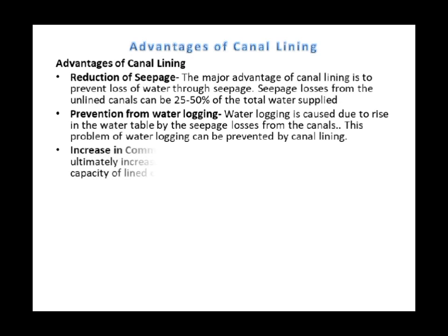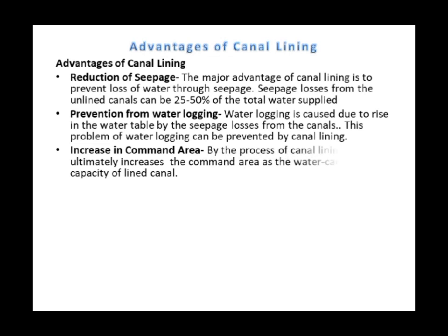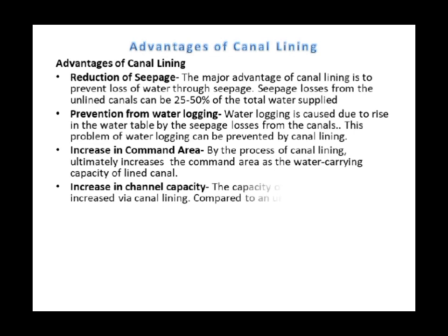Increase in command area. The process of canal lining ultimately increases the command area as the water carrying capacity of a lined canal is higher. Increase in channel capacity. The capacity of a channel can also be increased via canal lining compared to an unlined canal. Less maintenance.